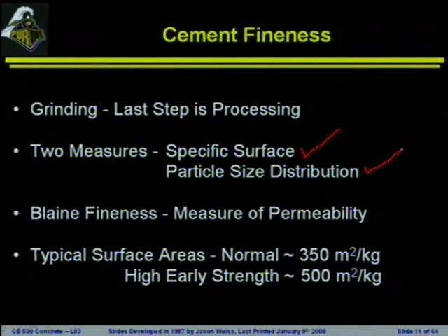Now, obviously, the surface area is going to be related to the particle sizes, and why would we be so interested about the amount of surface area, the size of the particles? It's going to start to control the rate of hydration or the speed of the reaction. The more surface area there is on the particles, the more that these particles can start coming in contact with the pore solution or the water, and they're going to react faster. So one of the things that we really want to keep in mind is, in addition to the chemistry of the system, the surface area or the fineness of the cement powder is going to be incredibly important.